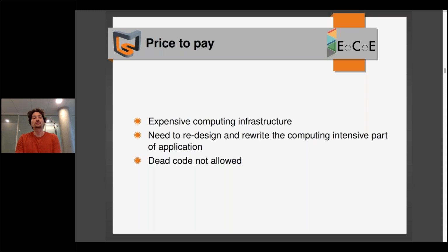Here on FPGA, if you have some part of your design that is implemented on the FPGA and is not used, it's part of the device, a piece of silicon that will not be used for your computation. So here you lose a lot when you have that code. That's the problem: it's very efficient potentially, but very specific to one single problem. And if the problem changes a little bit, then the design has to be changed a little bit as well.